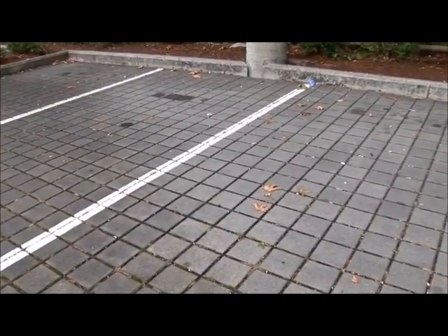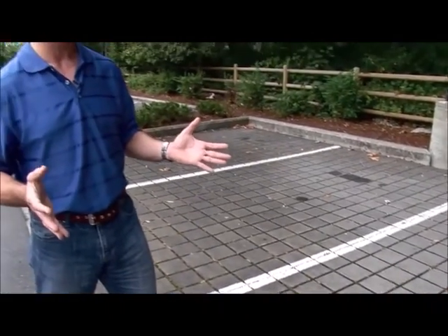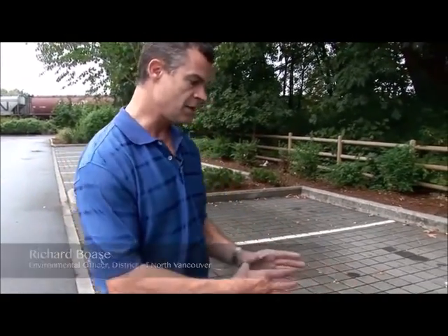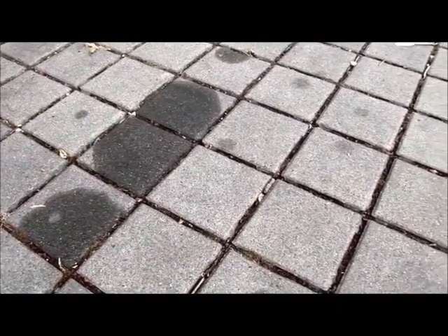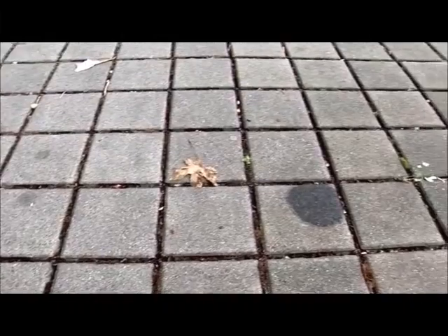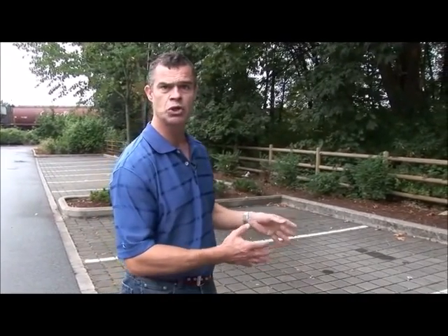So what we're looking at is a method that we can use to create more or less a porous kind of parking lot surface. The blocks here fit together, but they leave probably about a half an inch gap between the blocks that allows rainwater to land on this surface and then soak into the ground underneath the surface. We get some benefit in terms of, you can see the little bits of pollution and oil that fall off the cars. That material, when it rains, gets carried in between the cracks, moves into the soil where there's some natural aerobic decomposition that takes place, and we actually help reduce some of that pollution.